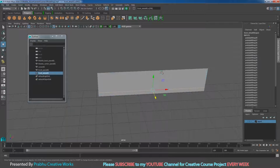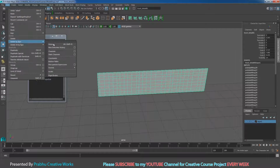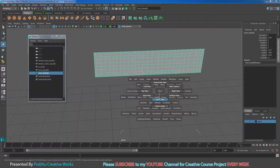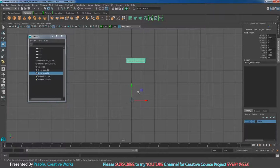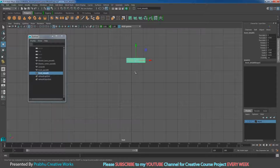So right click and choose object mode. I will select this object, go to edit, delete by type and choose history. So now my history will be gone. Go to front view. So see here our pivot has changed over here. So I will select this object, go to modify and choose center pivot. So I will select my object.